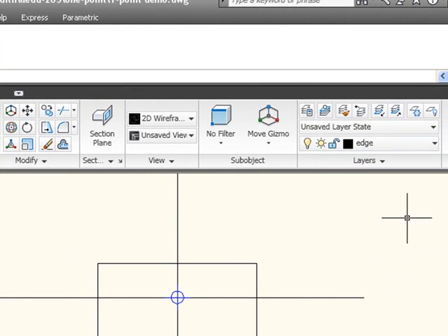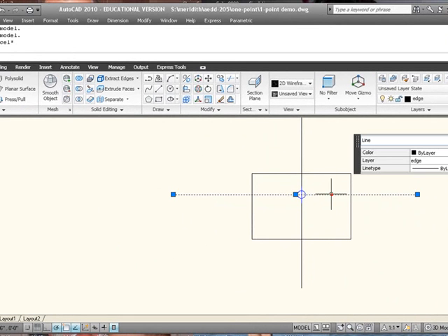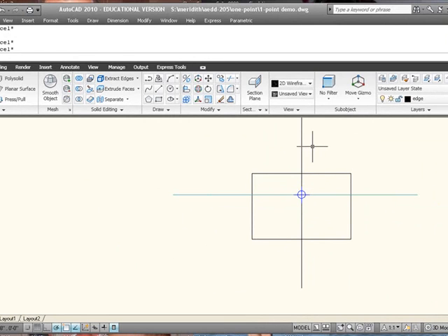Anything that is going away from us, so either from this corner and for instance the top edge of the wall, should go through the vanishing point. The bottom edge of the floor here and the wall should go through the vanishing point. So we're going to start to lay out these wall lines by putting those extra lines in. So let me just put some things on the right layer. We can get rid of this center line here. That's just how we figured out where the vanishing point was.